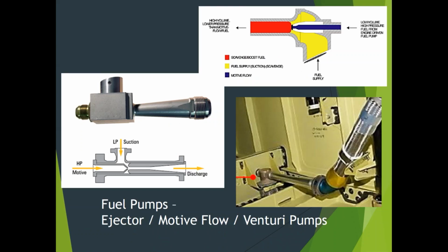So if our electrical system stops working, if we don't have power to the plane, we absolutely, and this is part of 14 CFR Part 25 design requirements, fuel must still make it to the engines even if we lose all our electrical systems and everything else on the plane. Even on wing-mounted planes, the collector tanks tend to be downhill from the engines.